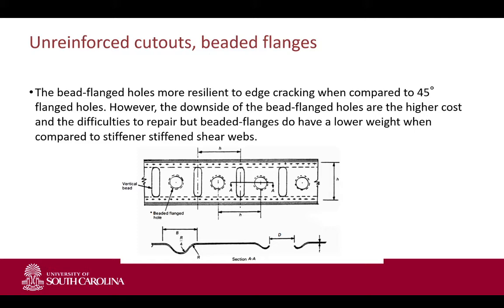It's in order to verify that you can hold the ultimate stress. So you load to ultimate stress, you hold it, and then they verify, okay, it can handle ultimate stress, or ultimate force, as the once in a lifetime force that an aircraft can see. Often a perfect design would basically fail after 3.1 seconds.